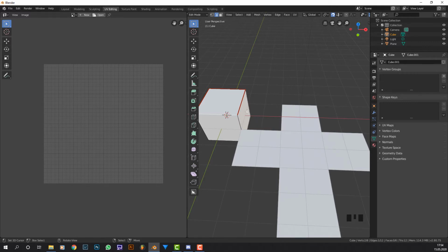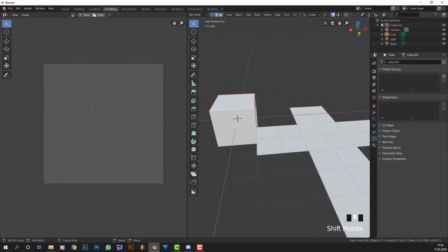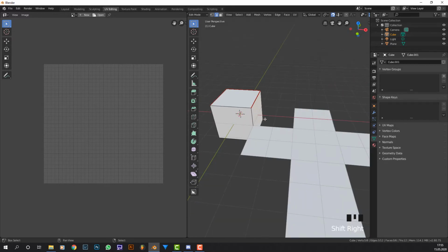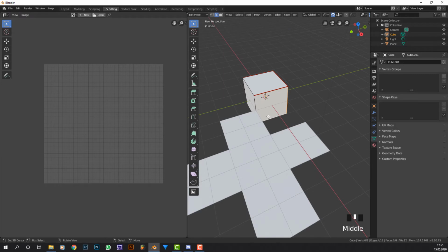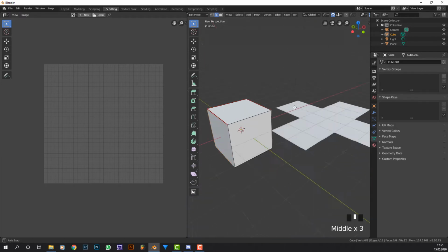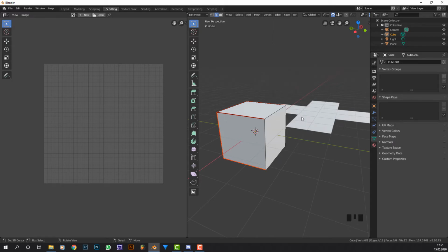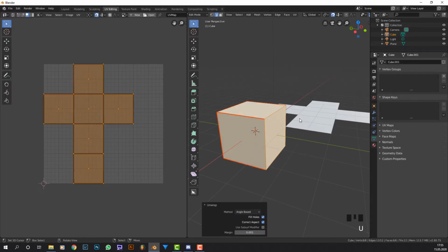But basically we see that this face, which is right next to this face, doesn't have connections over here. So basically this side is this side is this, and that side is the bottom side, and same on the other side. So I'm gonna place in cuts like this, so it makes a C and an inverted C, like the letter C. Then I'm gonna press mark seam, and if I were to unwrap that, it gives me this result.